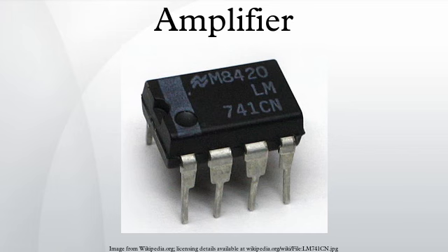Often the bias voltage applied to set this quiescent current has to be adjusted with the temperature of the output transistors. Another approach is to include small-value resistors in series with the emitters. Class AB sacrifices some efficiency over Class B in favor of linearity, thus is less efficient. It is typically much more efficient than Class A.